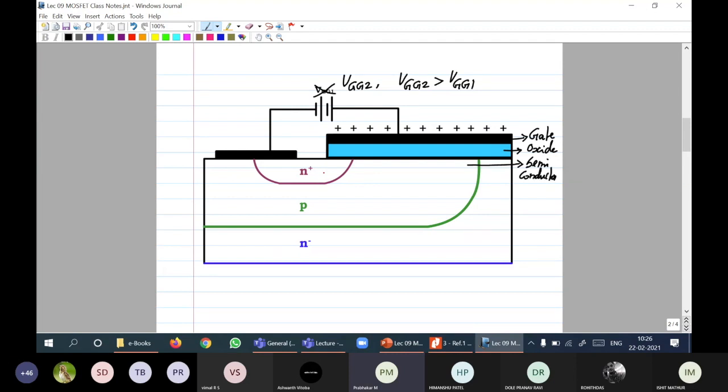In fact, it is called as MOS capacitor. Therefore, when you apply a positive potential to the gate, negative potential will automatically be induced, right? And the amount of negative charge carriers that are induced will be the same in magnitude due to capacitance effect. This is one way, easier way of understanding. Another way is, because the applied potential has increased, the width of the depletion layer will increase. Earlier, if it was thinner, now it will become thicker.